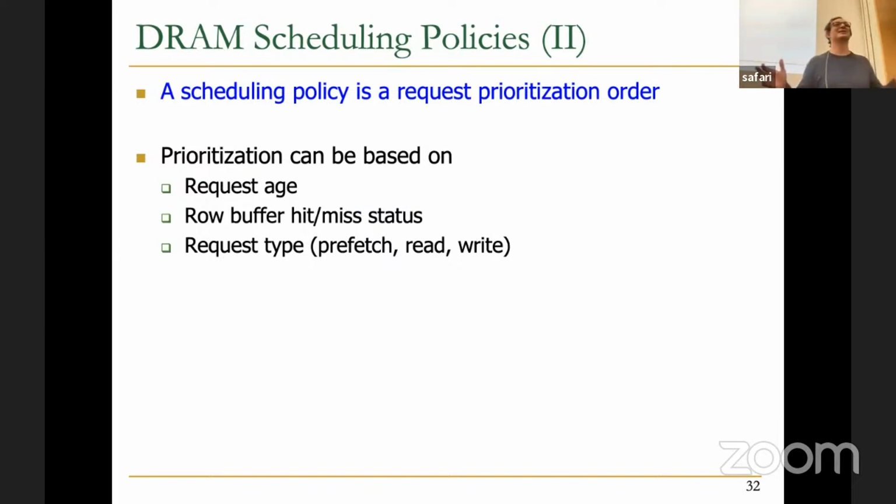Actually, you have to in DRAM. DRAM read requests and DRAM write requests are different because they do different actions to the memory bus channel, essentially. You cannot schedule a read while you're scheduling writes, because when you're actually writing, you're really pushing data from one side of the memory bus to the other direction. When you're reading, the direction of the bus needs to be turned around. And this is called bus turnaround time. Unfortunately, there's no way to read and write at the same time concurrently through the bus. You have to switch the bus direction, and this introduces delays. This introduces special delays like tWTR, tRTW.